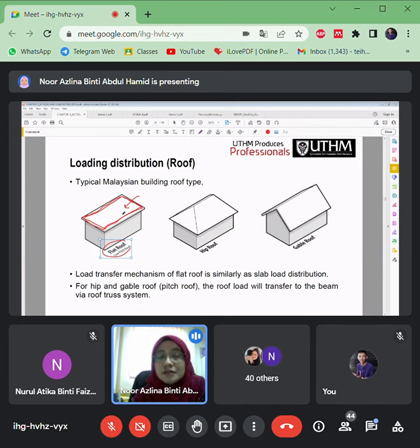Determine the type of this slab, either one way or two way slab. So for a one way slab, it just distributes the loads to these beams. For a two way slab, it should be a portion for a triangle and a portion for a trapezium, which is the same load distribution as for the slabs.